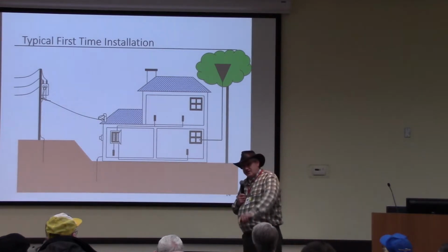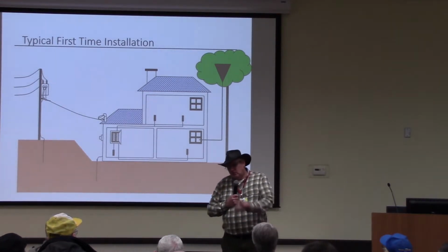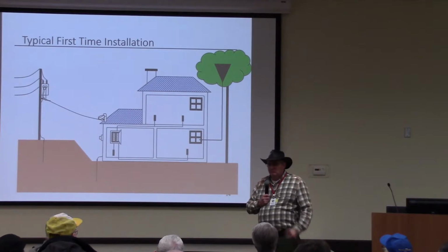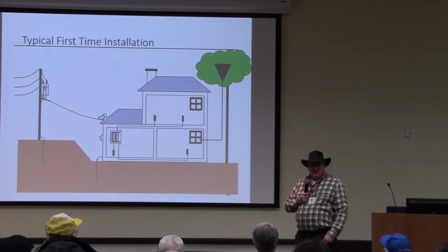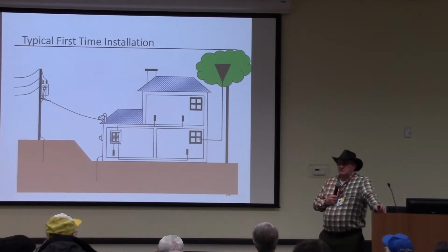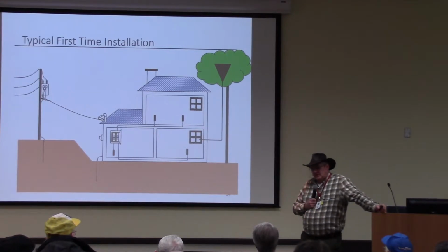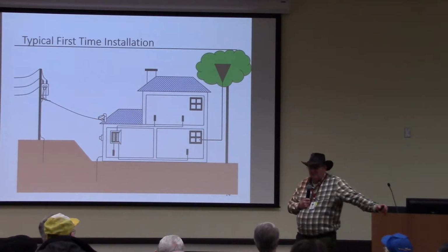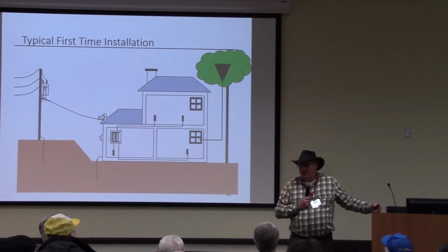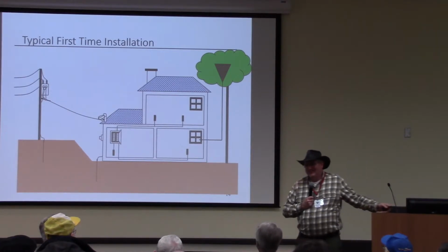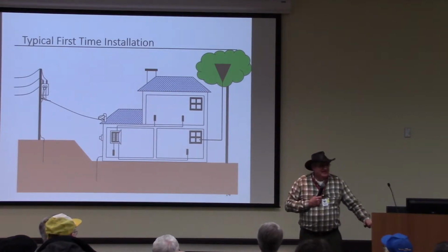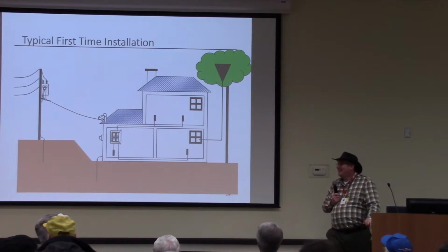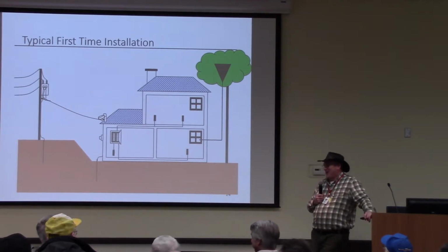Now if I disconnect it and lay it over to the side, about what's the distance from the end of your connector to any local metal object? A foot, okay? Remember I told you a little earlier that a leader formation was 50 feet? Okay, what's that foot doing for you? Not enough. Throw it out the window. Needs 49 more. Needs 49 more.